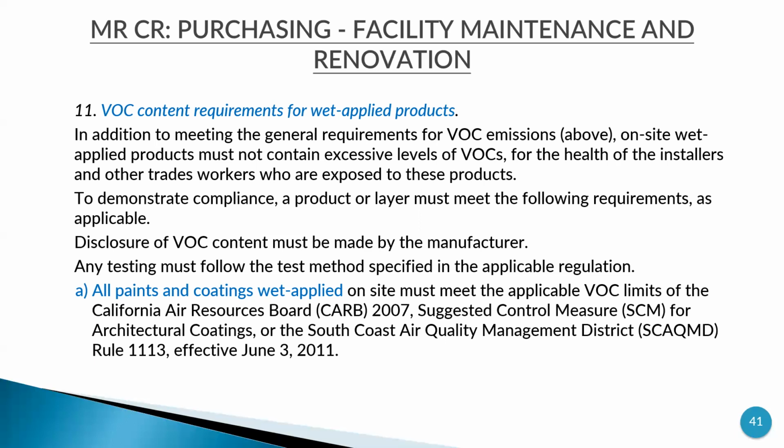We do use rock wool insulation, so you have to be very careful, right? There is a company that supplies rock wool. If it touches your hand, you will get immediate irritation because it has a crushed glass kind of stuff in it, a fiber kind of thing.